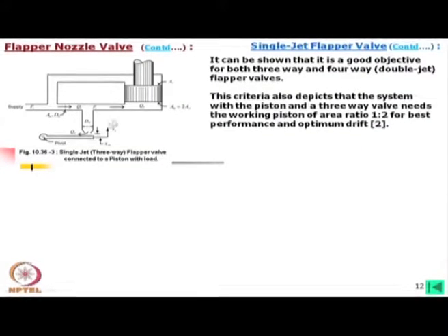You will find that when this is at the central position, this spool, this piston cylinder what we have called, is basically controlling a spool that should be in such a position that that spool is also in the null position. But due to leakage and error, when this is in the mid position, what it is controlling is not in the null position. So this null position and that null position may not match. So that is called drift. Now, there is also a technique that we can control the drift.